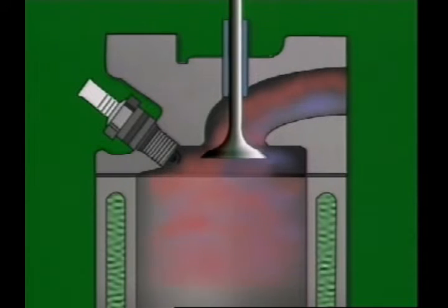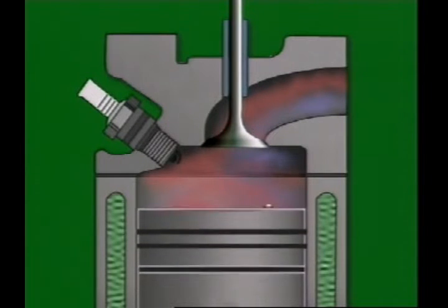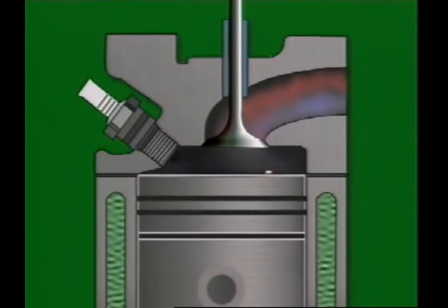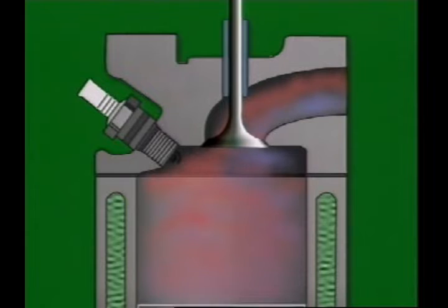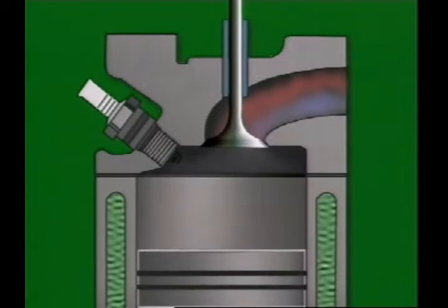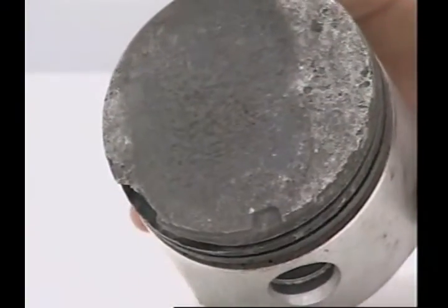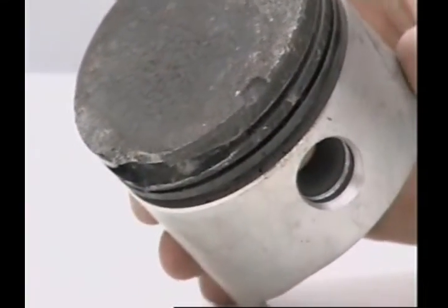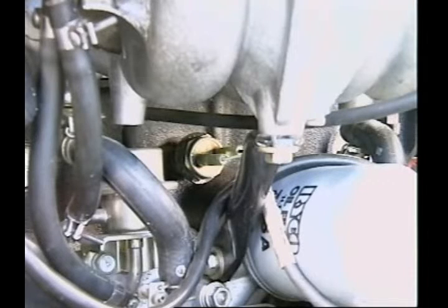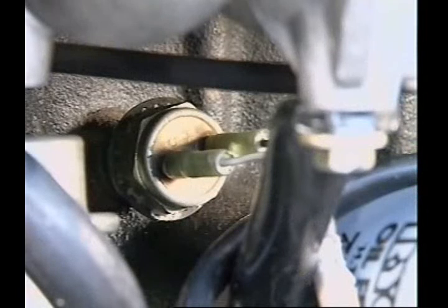Pre-ignition occurs before normal combustion, when something in the combustion chamber heats up enough to ignite the mixture before the spark plug fires. A mixture may also ignite simply because it is unstable under the higher heat and pressure. Detonation and pre-ignition can cause severe damage and must be avoided. Engine management systems use knock sensors to detect detonation, and they retard ignition to stop it.